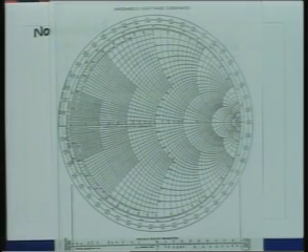So, depending upon whether we are doing calculation for the impedances or admittances, and if I require the phase angle measurement in the complex gamma plane, then appropriately the axis has to be rotated by 180 degrees depending upon whether I am using the impedance or admittance.